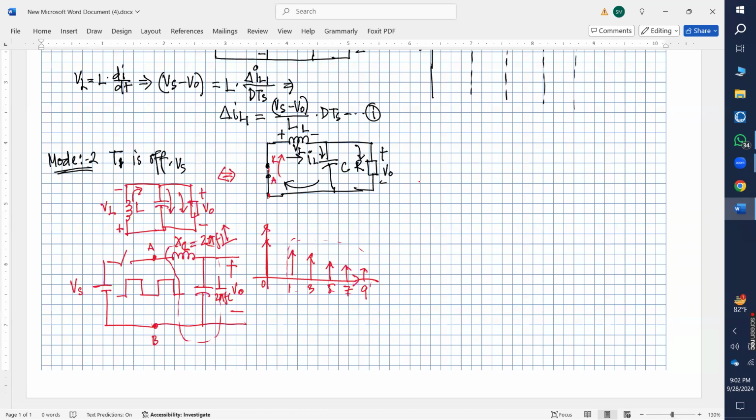But as soon as it gets the high frequency components, the higher order it gets, with the increase of frequency, this impedance will be higher, right? And the capacitor impedance will provide a low path. So all the high frequency components will try to get suppressed by this inductor, but if they manage to pass through the inductor, this capacitor will provide a short path for the high frequency components, so that they go through the capacitor rather than going to the load.